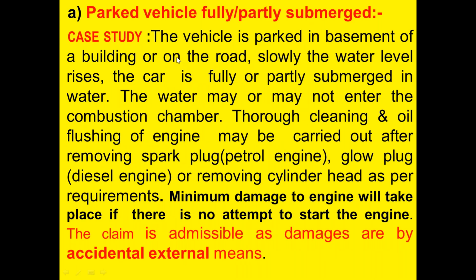Parked vehicle fully or partly submerged. Case study: the vehicle is parked in the basement of a building or on the road. Slowly the water level rises. The car is fully or partly submerged in water. The water may or may not enter the combustion chamber. Thorough cleaning and oil flushing of the engine may be carried out after removing the spark plug in petrol or glow plug in diesel, or removing the cylinder head, as per the requirements. Minimum damage to the engine will take place if there is no attempt to start the engine. The claim is admissible as damages are by accidental external means and inundation.